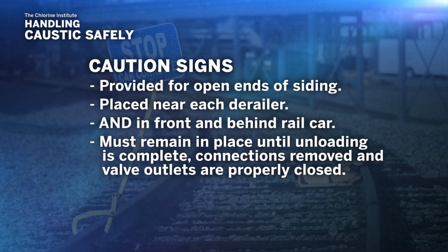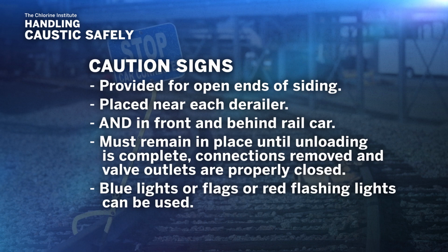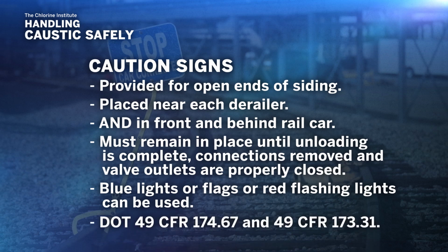Caution signs must remain in place until unloading is complete, the connections are removed, and the valve outlets are properly closed. Blue lights or flags or red flashing lights can be used in conjunction with caution signs to warn of unloading operations. See DOT Regulation 49 CFR 174.67 and 49 CFR 173.31.